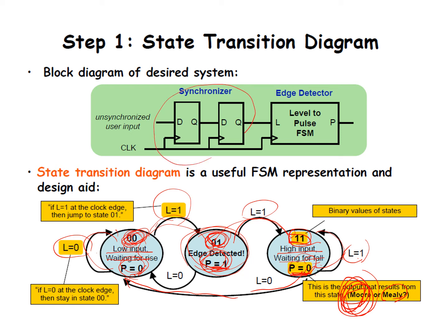In this case, at the input, we use a double synchronizer to eliminate metastability issues. You have to use this synchronizer.